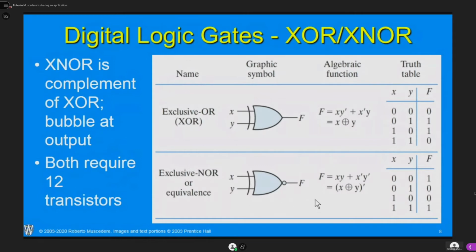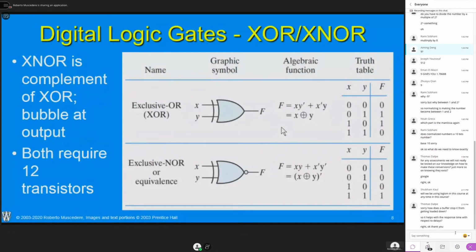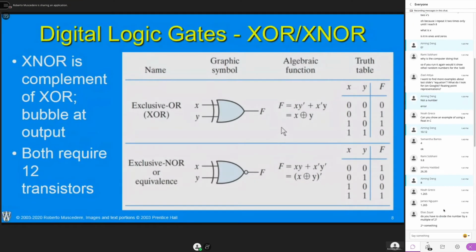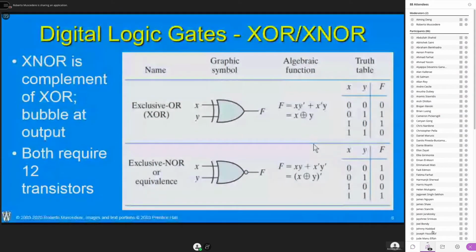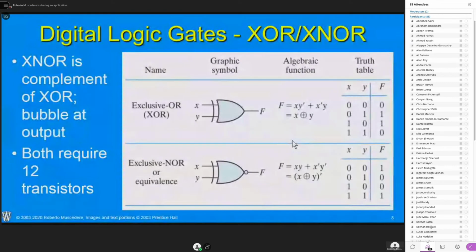Okay, so it comes up often. If I want to compare two numbers, it's likely your circuit is using an XOR gate to do that. It's one of the fastest ways. We can do it in parallel, just run the outputs through a bunch of XOR gates or XNOR gates, and we just look to see, we AND all the results, or we OR all the results, I should say, and if it's a 0, it means it's equal. It's very simple. Very, very easy to build, very fast.